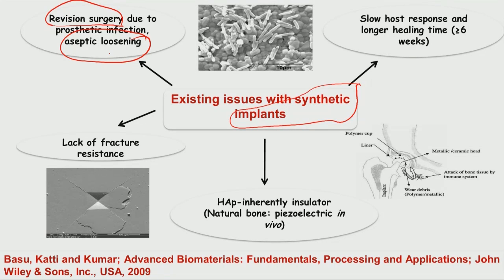weeks or more required. Third one, in the context of bioceramics particularly, hydroxyapatite is inherently an insulator material, whereas natural bone has a piezoelectric property in vivo. And fourth one is the fracture resistance property. Ceramics are primarily weak in terms of the fracture resistance property.